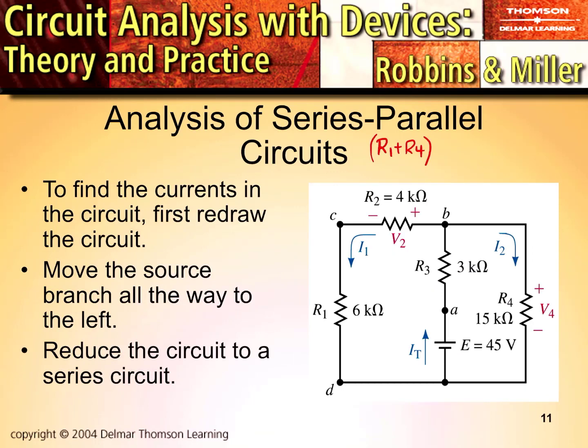All right, so here's an example of where we need to redraw this circuit, of course, with the source on the left, loads vertically on the right, labeling all current division and points. Now, notice how we have a current division node right here.